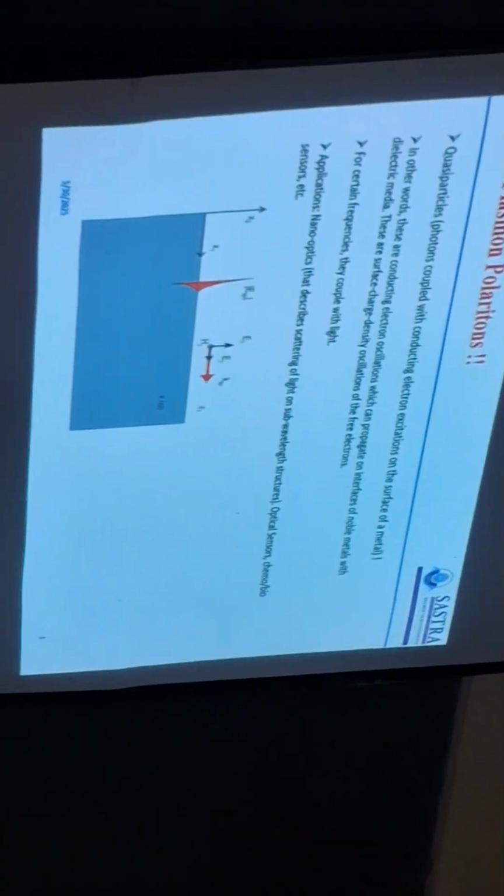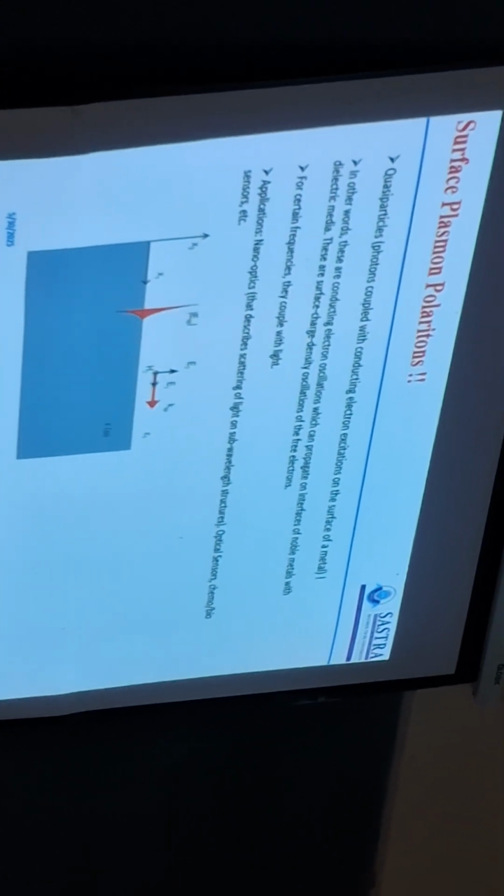So, when you look at Naveen's presentation, the device has three terminals: source, gate, and drain. Source is where the electrons get injected. Gate is basically what controls the electrons in the channel. And the drain is where the electrons get collected or where the current goes, depending on what you define. Generally, the source and drain are interchangeable.